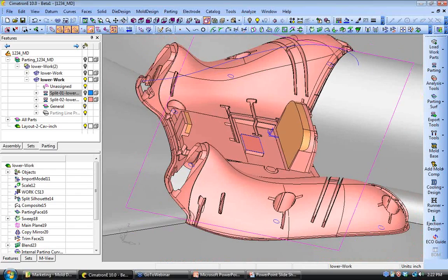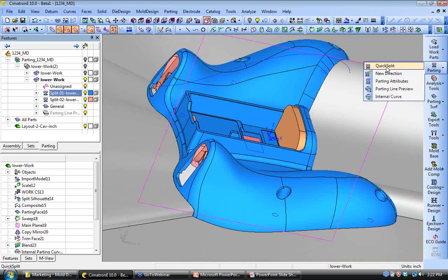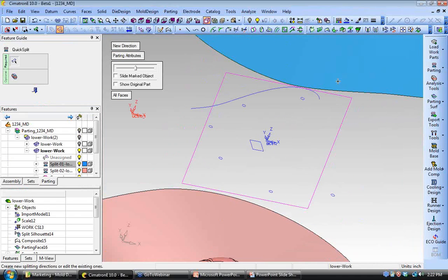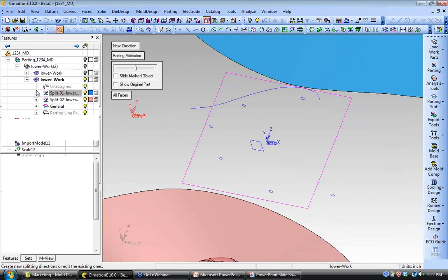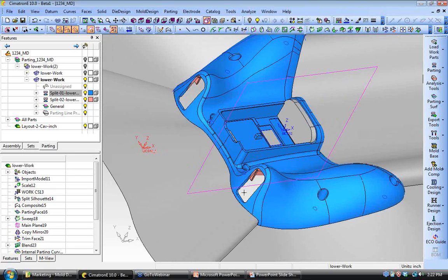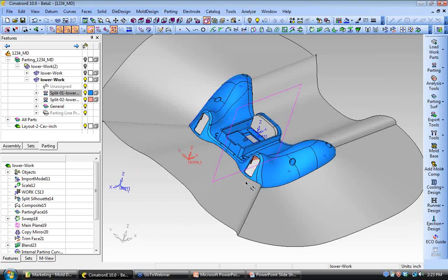Now, like before, we want to assign these internal surfaces as parting, so we can visualize a copy in both halves of the mold. And that really leaves only 2 windows in the part that I've left undefined here. But I'm going to leave those open for now to save time, but also to show how Cimatron can keep moving ahead in the design process without worrying about gaps or undefined areas like this. And I can come back to the parting area anytime for changes or adjustments, but really the next move is to work on the mold itself by creating the cavity blocks.